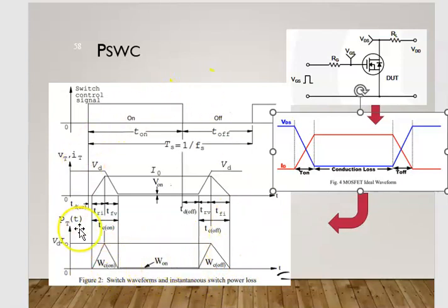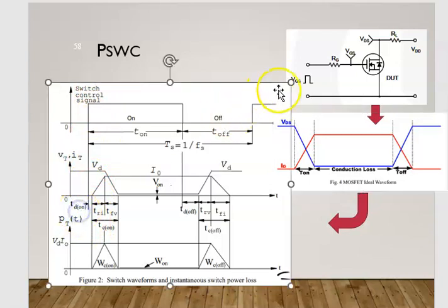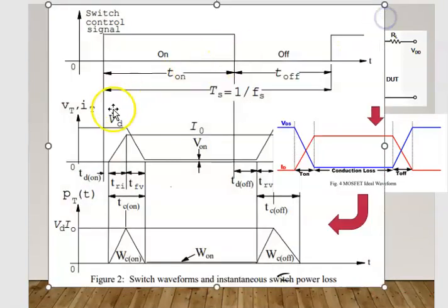So the sum of the switching and conduction times the frequency that we apply, we shall get the total losses of the system or of the switch. Okay, so you can see here when the switch starts, we still have a time delay. This TD here is time delay. You can see, even though we apply the switch on at the gate, we have a delay.